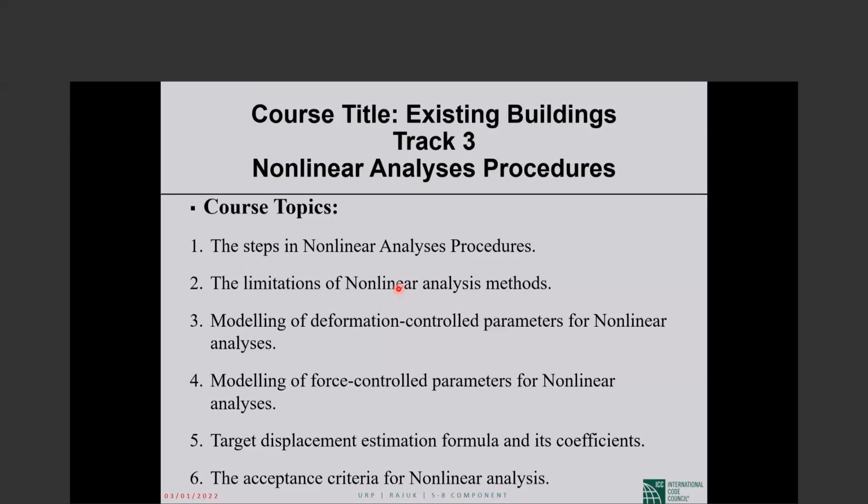Tell the software to use just one, and then use more modes, as usual, a number of modes such that the effective mass is more than 90%. And then if in any story the difference between these two results of the story shear is more than 30%, it shows that higher modes are important.